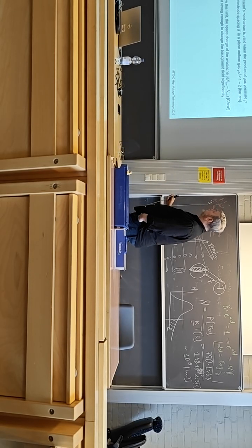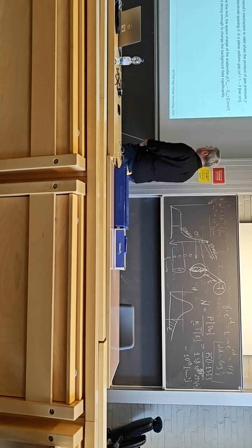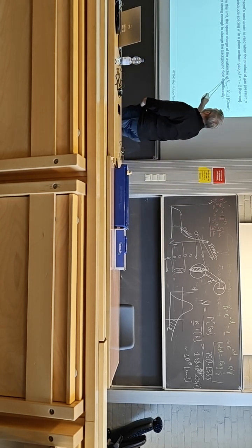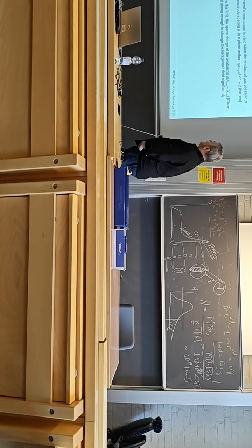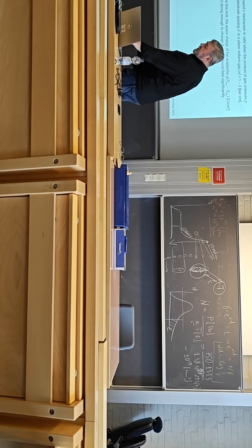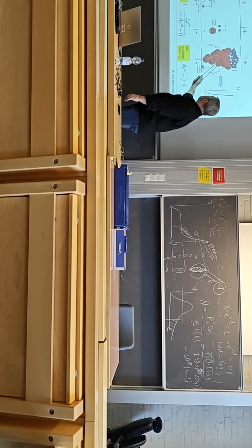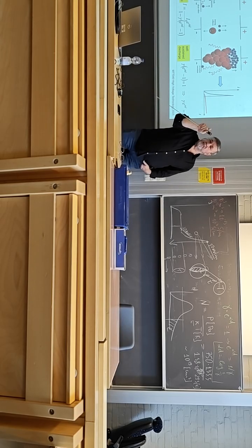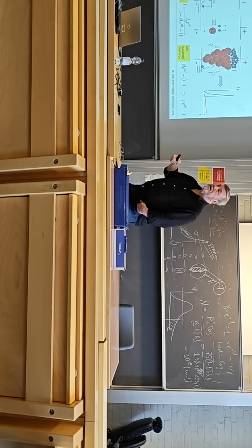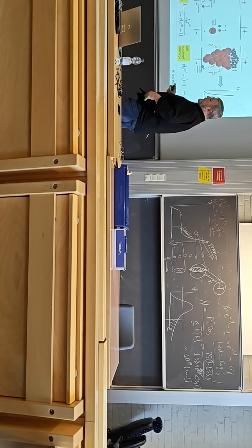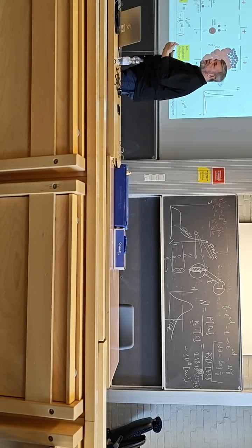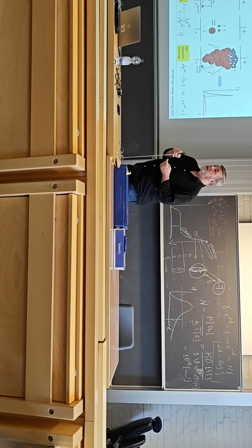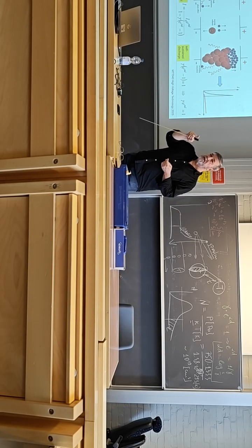That's what I mentioned already. It's a streamer type of breakdown. Below this limit, the space charge of the avalanche is rather low. So we have a certain number of ions, a certain number of electrons per unit volume, their concentrations. If we multiply this concentration with the elementary charge they carry, we will have coulomb per cubic centimeter.